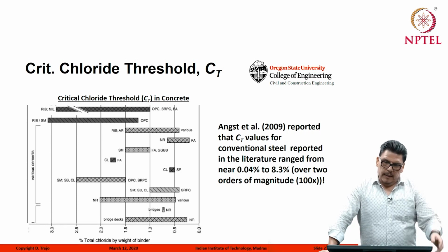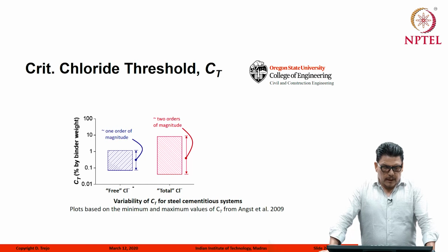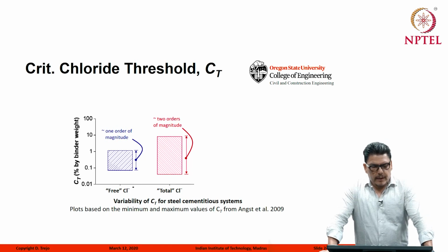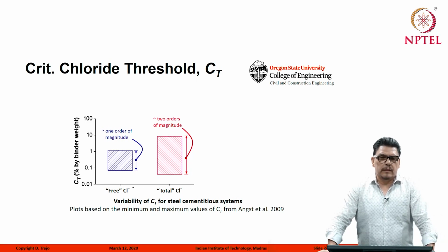One of the things that we've seen is that there are several issues: how you test your chlorides, and how you test the critical chloride threshold, and I'll talk about these now. One of the things that we look at is what test you use to test the chlorides. One could be the "free" chlorides, and I have free in quotes intentionally, because free could be water soluble, it could be pore extraction. It's really not clear on a lot of this what this was.